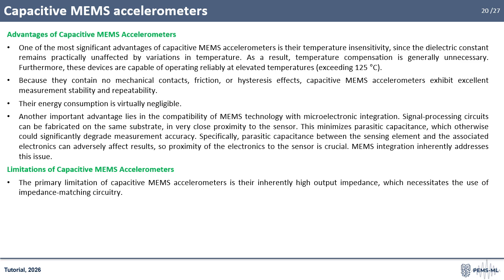The effect depends on crystal orientation, dopant concentration, and temperature, with temperature being the main limitation. Piezoresistive MEMS accelerometers offer high output voltage and low impedance, ideal for direct signal processing. Their main drawback is high temperature sensitivity, requiring temperature compensation in wide temperature ranges.